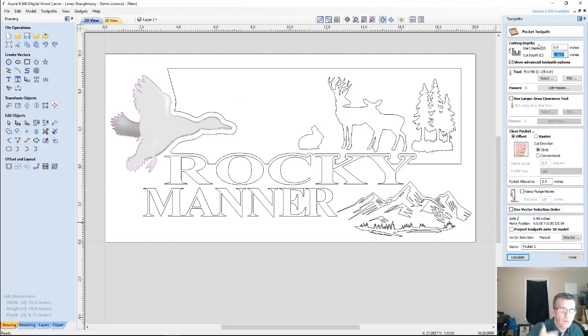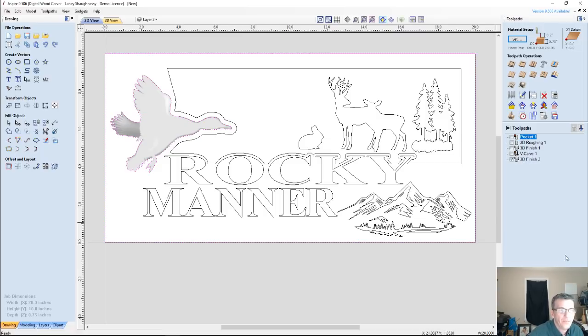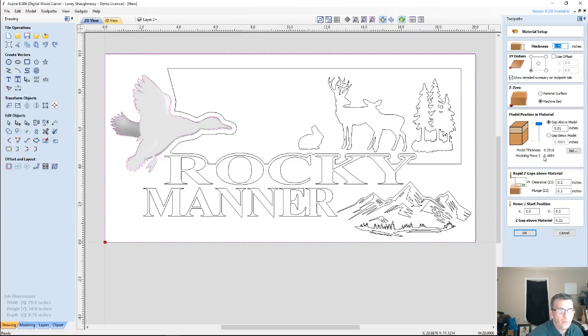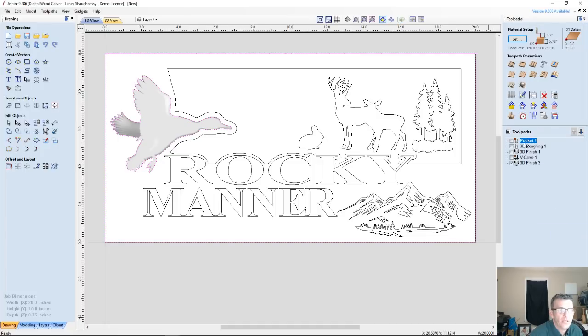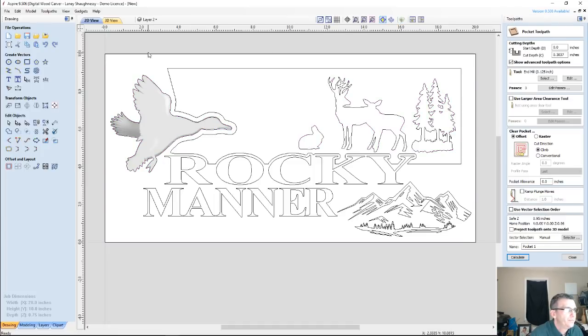Now I need to, again, do my math. So 0.4884 is the number that I'm subtracting from 3/4. So on my pocket cut, .75 minus 0.4884 equals, that's going to be my depth of cut.